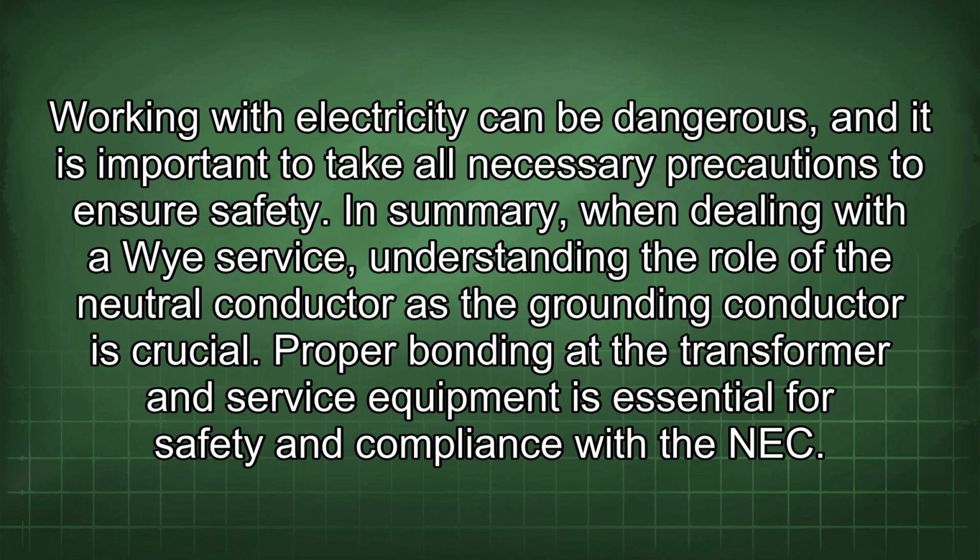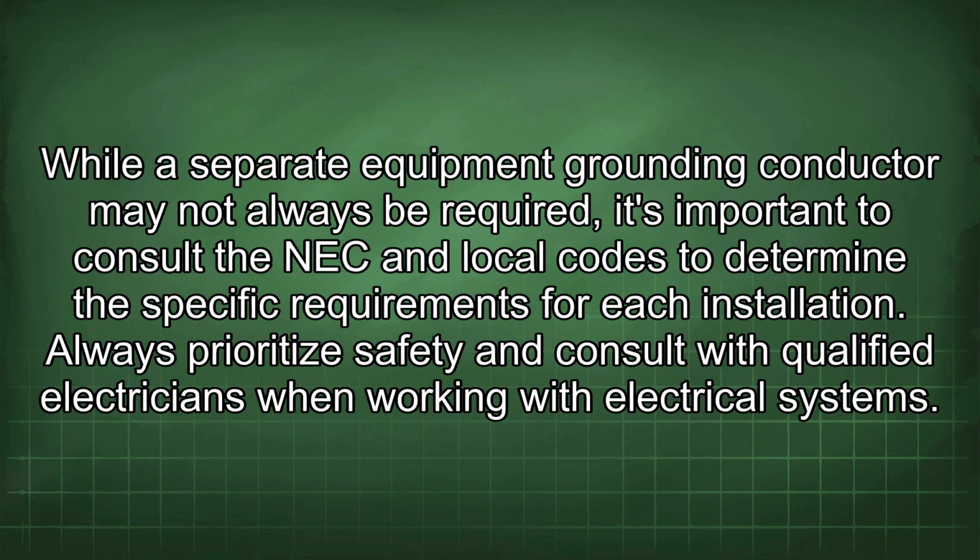In summary, when dealing with a Y service, understanding the role of the neutral conductor as the grounding conductor is crucial. Proper bonding at the transformer and service equipment is essential for safety and compliance with the NEC. While a separate equipment grounding conductor may not always be required, it's important to consult the NEC and local codes to determine the specific requirements for each installation. Always prioritize safety and consult with qualified electricians when working with electrical systems.